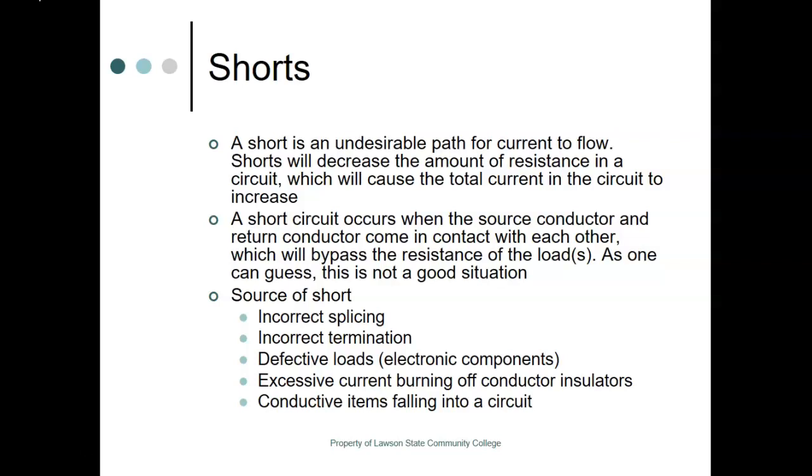Sources of shorts are things like incorrect splicing or termination, defective loads, excessive current that burns off conductor insulators, or conductive items falling into a circuit. In other words, about the silliest thing you could do would be to take a piece of wire and stick it in both holes of a socket. That won't take long to burn off.